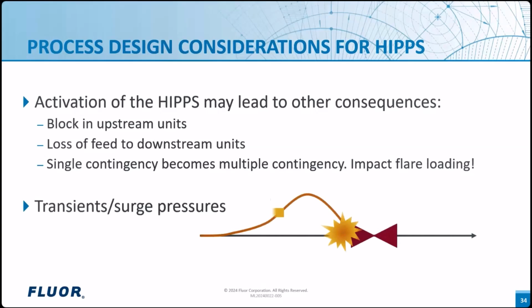In liquid pack systems, there are additional considerations. The fast closure of an emergency shutdown valve or tripping of a pump can result in hammering or transient pressure waves. This can require specialized assessment to ensure protection against transient pressures. An interesting trade-off arises due to the HIPPS favoring fast closing valves and transient protection favoring slower closing times.